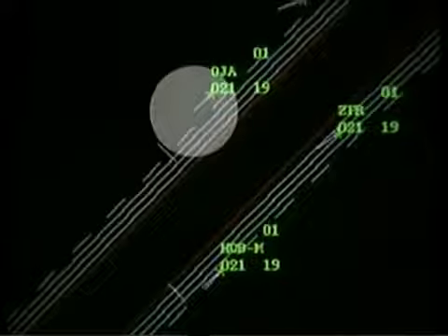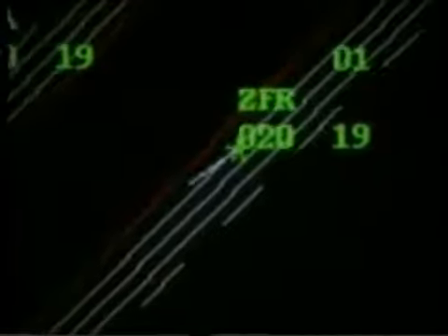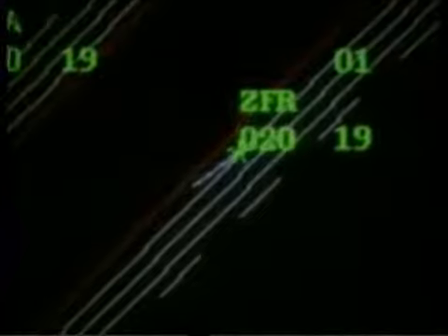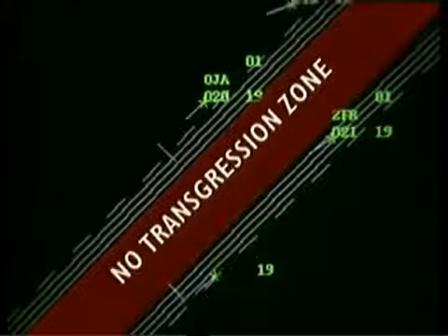The target update is faster than current approach radar systems. The radar has a predictor line that shows the predicted flight paths for the next 10 seconds, and computer-generated warnings assist in alerting the PRM controller when an aircraft strays from the approach course towards the NTZ. The NTZ, or no transgression zone, is depicted on the monitor controller's display. The NTZ is 610 meters wide.